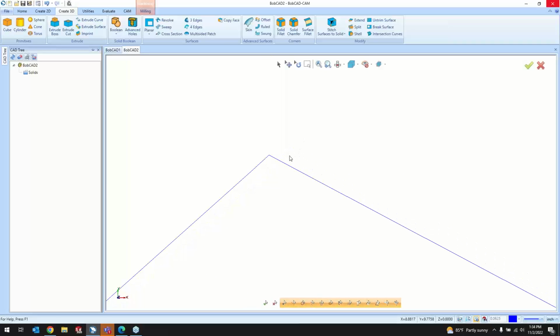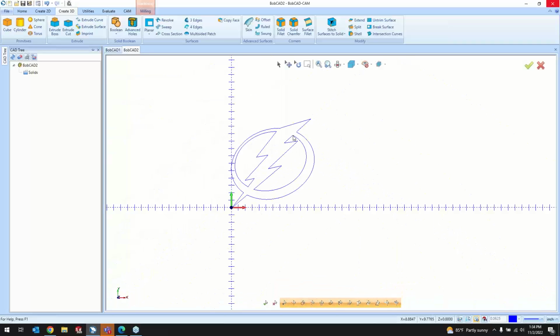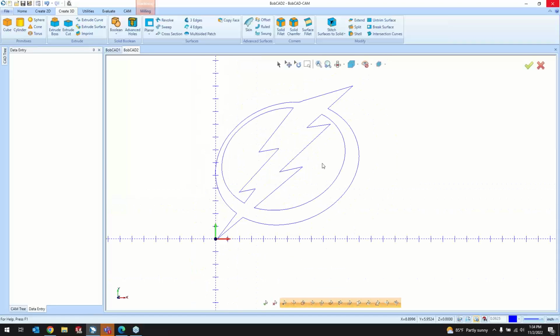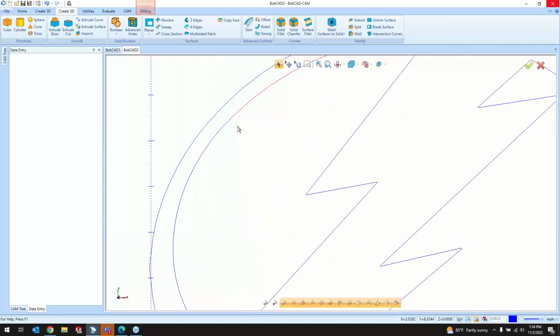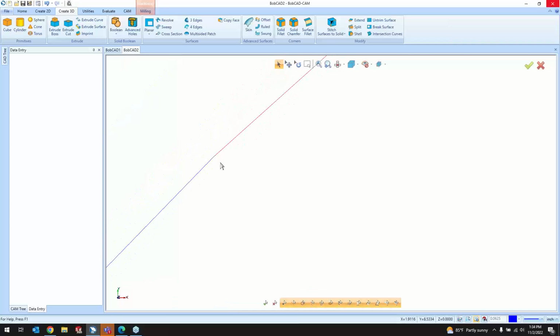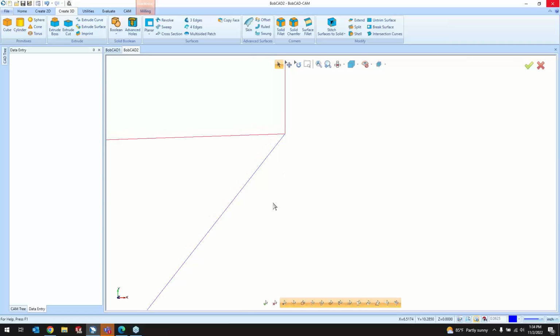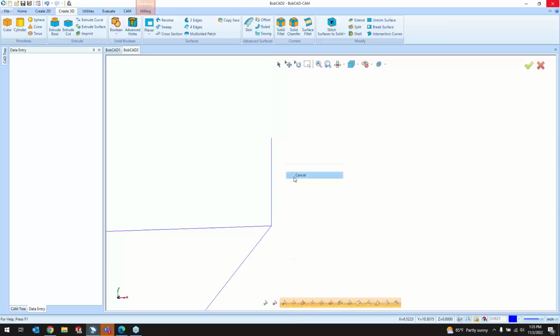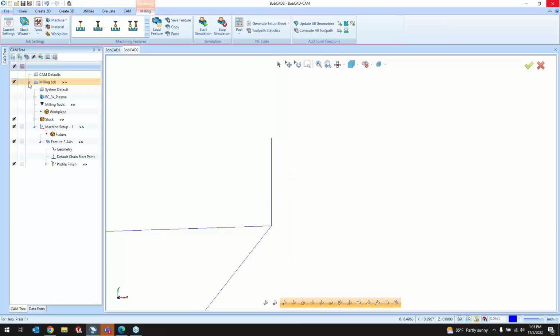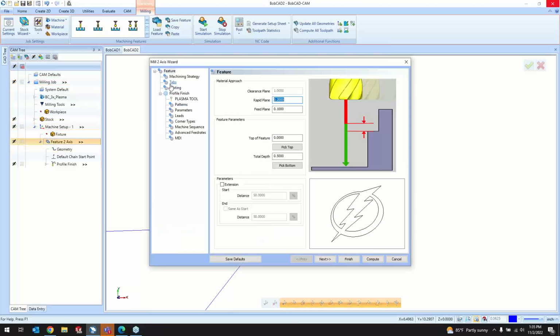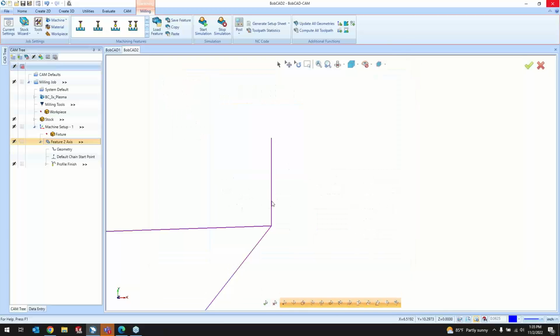And if I wasn't able to find that, this is a good transition here. If I wasn't able to find the bad geometry in the file, I could go here to my select mode. I could hold shift and chain select part of the drawing here. And it's showing that at a certain location where it stops, either at this point of the arc or this point of the arc, yeah, there's that extra line that I saw in the profile here under the tabs. I was wondering what that was. That is this guy here.